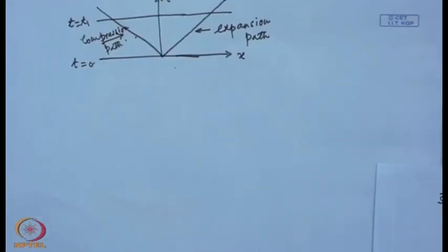Now, what we have covered today is basically wave motion in one dimension, where we first linearized the continuity equation and Euler's equation, assuming that the disturbances are small, and we have seen that the disturbance propagates with a constant wave speed, which happens to be the speed of sound, implying that small disturbance waves are isentropic and acoustic waves.